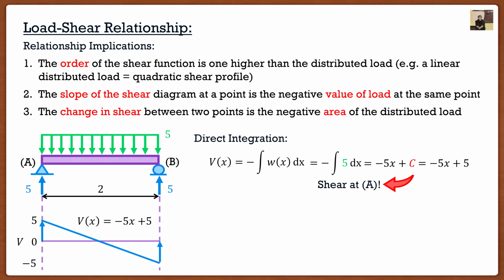It should always start and end at 0. Always. We start at 0, we popped up 5 because of the point load, then our shear force due to the distributed load came down linearly, and then the other support reaction was 5, so we pop back up, we ended at 0. So we can shade it in and we say, all right, here's our shear force diagram. Again, no cutting was needed, and I took way too long to explain it.